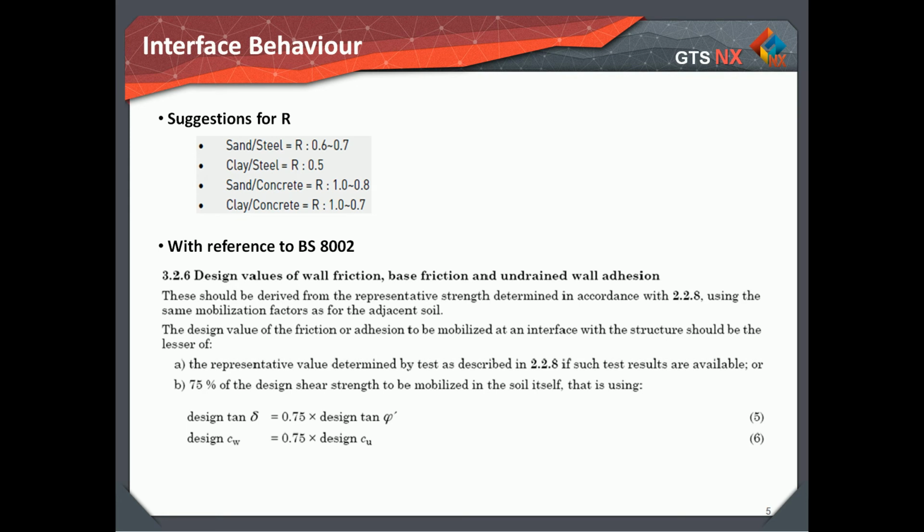The general strength reduction factors for structural members and neighboring ground properties are as follows. Checking the element size considerations calculates the interface material properties considering the average length, average area, or volume of the neighboring ground element when creating an interface. In other words, the average length and average area are multiplied by the virtual thickness in the equation below to calculate the tangent and normal direction stiffness of the interface.